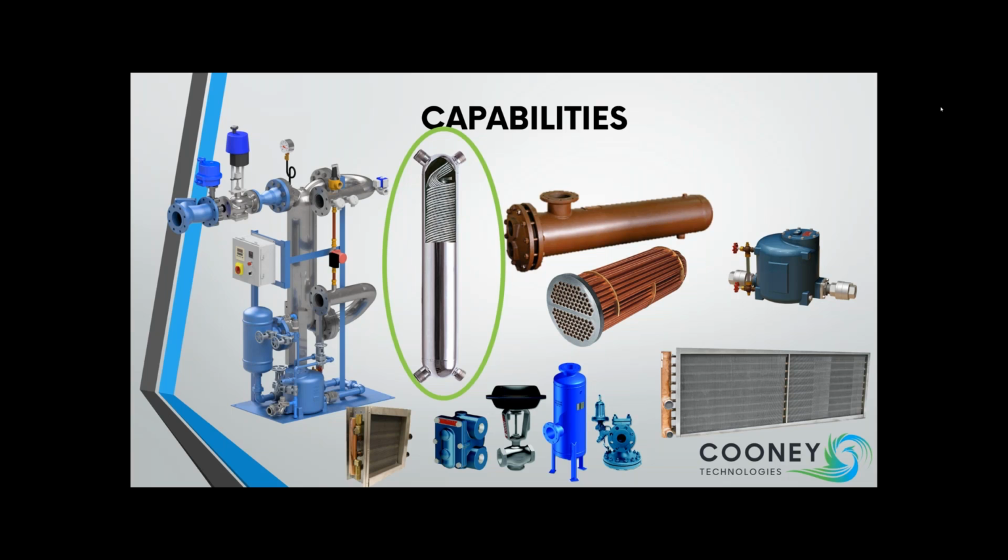You'll see the top right connection. You have your steam coming in, goes through a dimpled, braided, welded stainless steel tubing that coils down to the bottom of the exchanger, and the bottom right connection has the condensate that exits the heat exchanger. On the bottom left side, if you're using this for domestic water, you're going to have your cold water inlet here, and your hot water outlet is the top left. So as the cold water inlet comes in, it's basically a counterflow design.